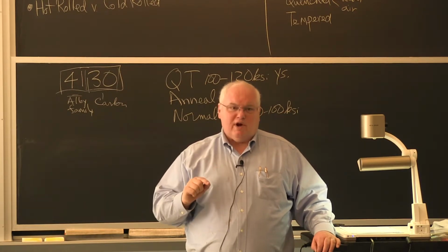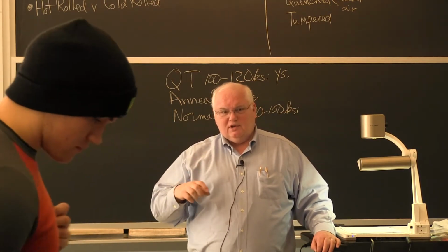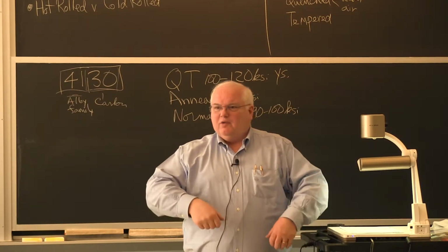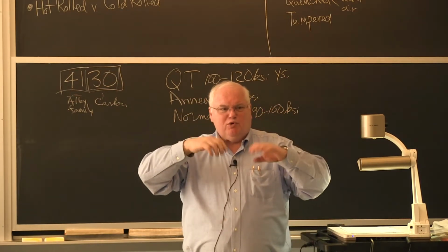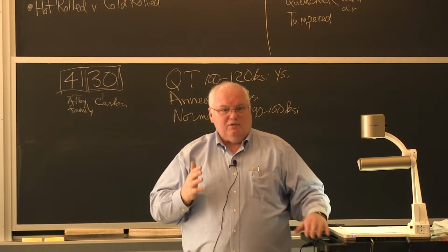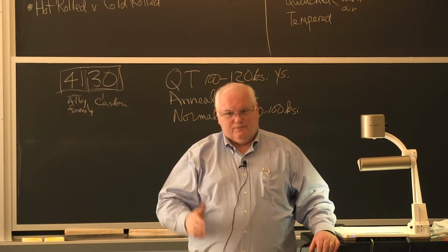And it had started a crack, and it grew by fatigue until it was like 60% of the way around, and on one jump the thing just broke. But the final failure was nice and ductile, the steel bent over and everything. Well, unfortunately the first part wasn't.